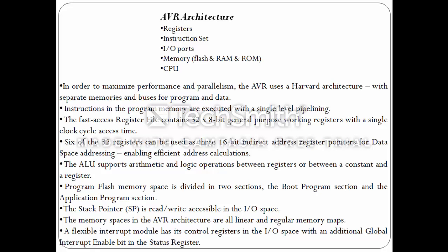The program counter, PC, commonly called the instruction pointer, is 14 bits wide, thus addressing 16K program memory locations. It contains the address pointer value of the current instruction. Each cycle, the program counter is updated to point to the next instruction.